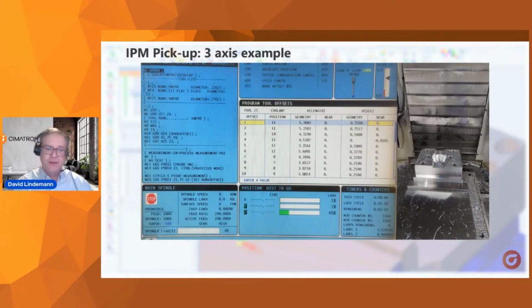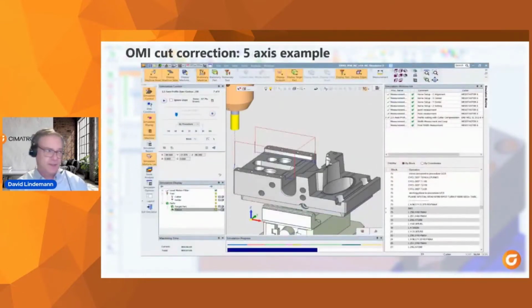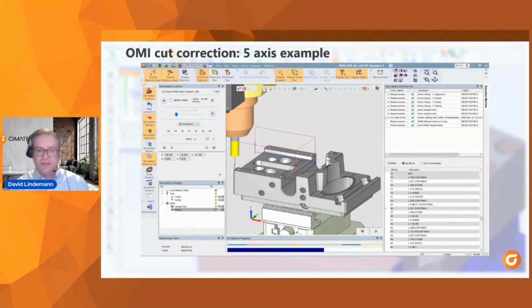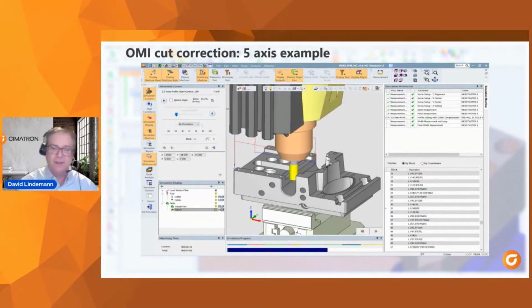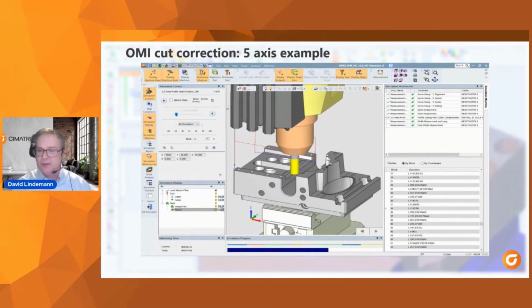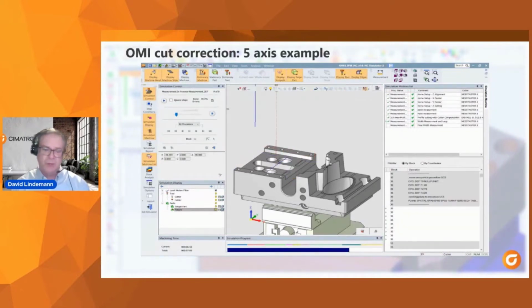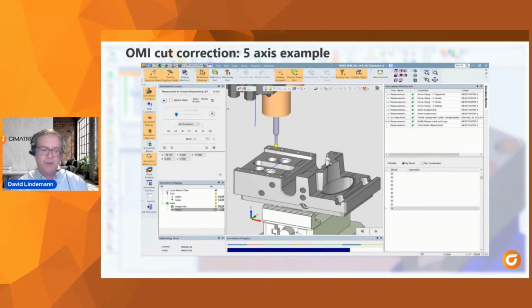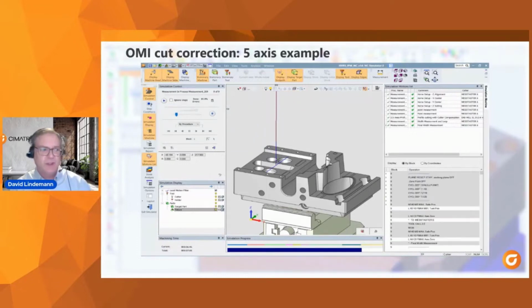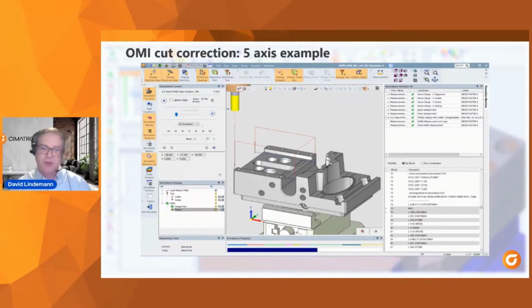Taking this further then, if we go forward with our 5-axis example, we're just going to do an inside cut along the trench of that part, and then we'll measure it, cut it again. And I just can't stress how important it is that I'm not taking this part off the machine to make that measurement, because the work it would take to put it back up would be so much time. And what if I didn't get it right? You can understand there'd be a big problem. I would scrap out this part.